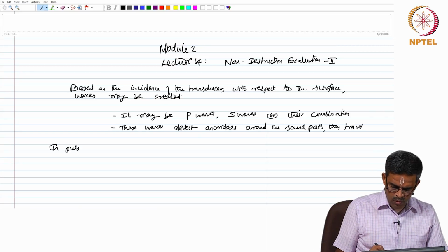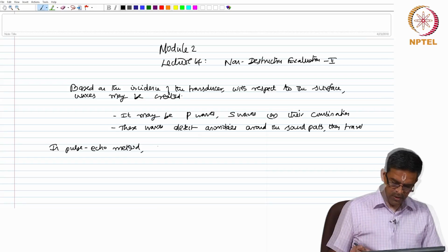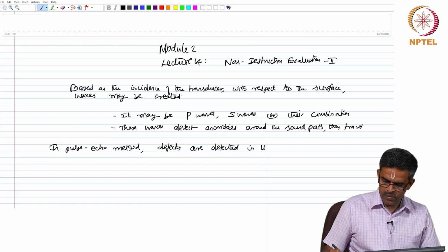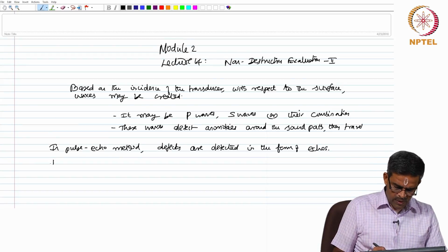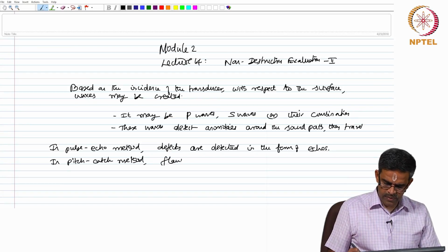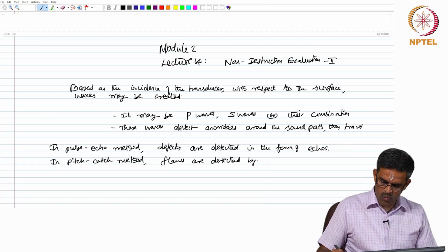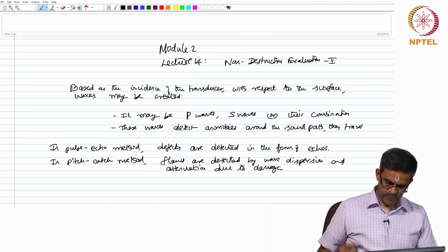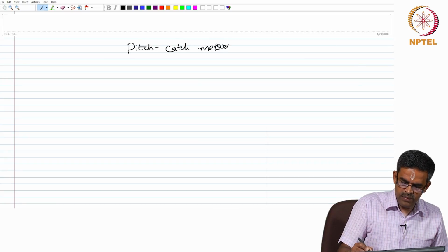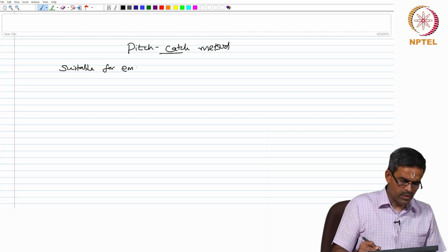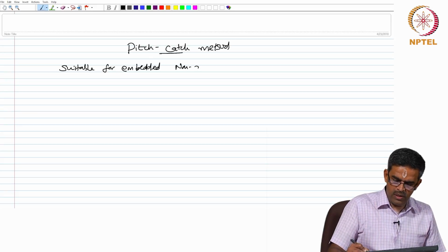In pulse echo method, defects are detected in the form of echoes. Alternatively, in pitch catch method, flaws are detected by wave dispersion caused due to damage. Pitch catch method is suitable for embedded non-destructive evaluation.